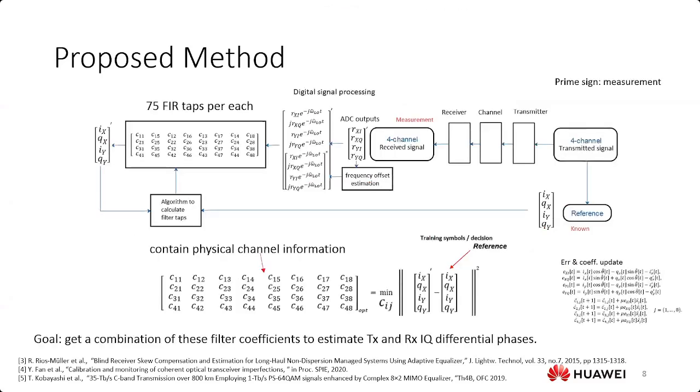For details, first, at the ADC output, we will transform these ADC outputs to another 4 ADC outputs, which are complex valued. We'll compensate the frequency offset using a phasor, and also multiply the quadrature parts of the 4-channel with the imaginary constant j, so that now we have 4 complex valued sequences, and we'll duplicate them to their complex conjugates, altogether 8 inputs.